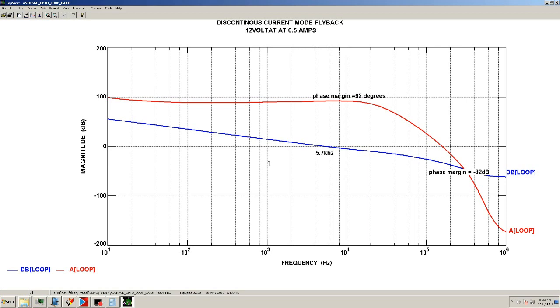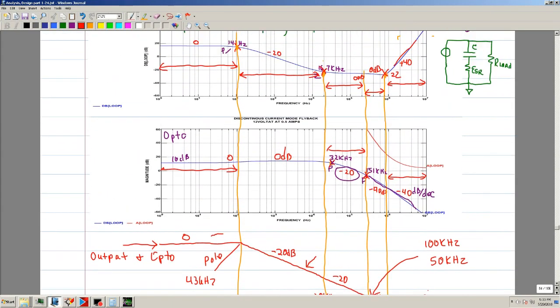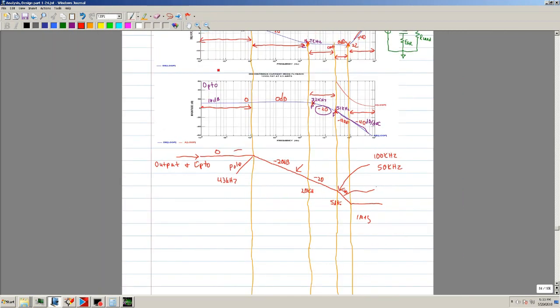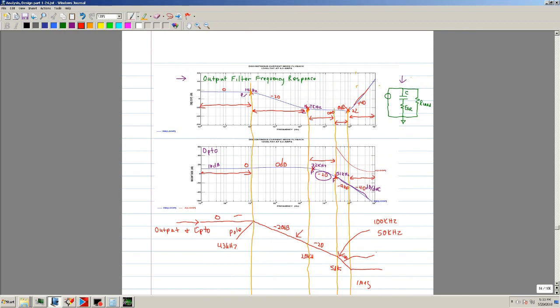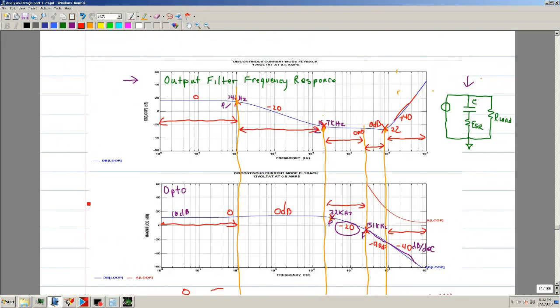So anyway, that's a good compensation. It looks like a very stable system. Basically that's how you compensate. You need to do these manipulations with SPICE. You don't have to draw it, but let the simulator do it for you, but at least have an understanding of what is happening. And once you have a feeling of what is actually happening, then the compensation is actually trivial, or not as complicated as one would think.